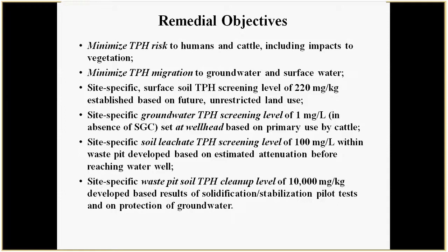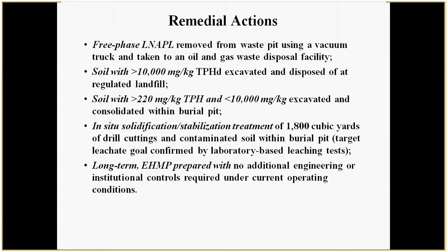Remedial action: all the free phase LNAPL removed from the waste pit with a vacuum truck. Soil with greater than 10,000 ppm TPH diesel excavated and disposed of. Soil with greater than 220 milligrams per kilogram TPH and less than 10,000 ppm excavated and consolidated within a newly designed and better aligned burial pit. In situ solidification and stabilization was carried out for 1,800 cubic yards of soil and drill cuttings placed in the pit. There's some references, including the case study, on how this was done. I actually don't have much experience in this. And then a long-term environmental hazard management plan was prepared. No additional engineering or institutional controls, just document where this stuff is and how to manage it.